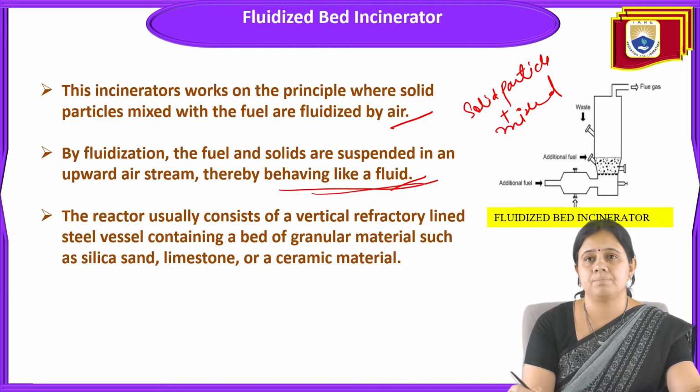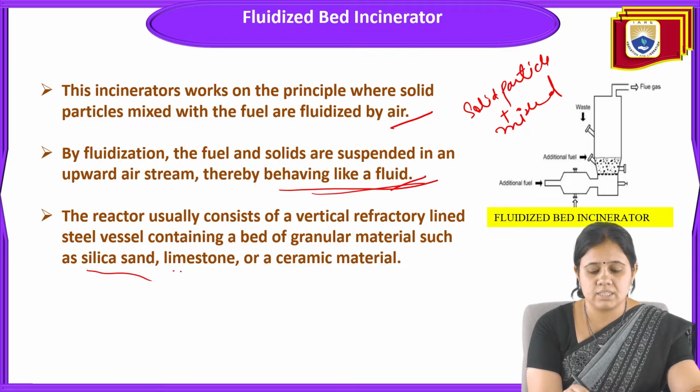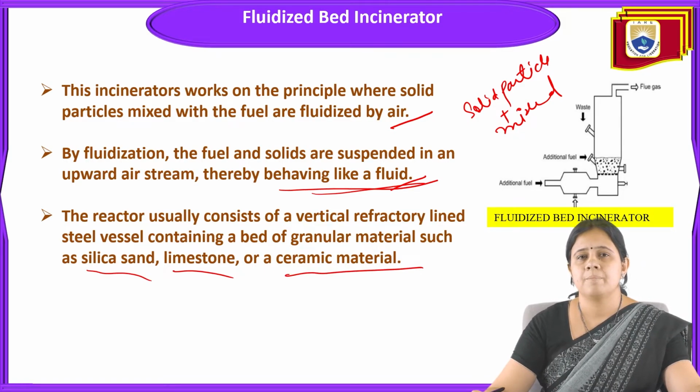like a fluid. The reactor usually consists of a vertical refractory lined steel vessel containing a bed of granular material such as silica, sand, limestone, and ceramic material. So these are three types of material that are used in this reactor.